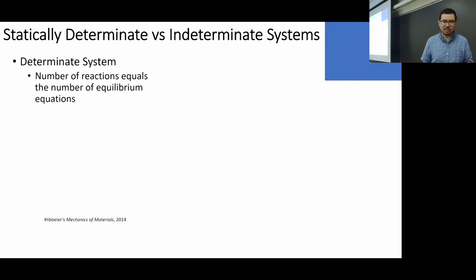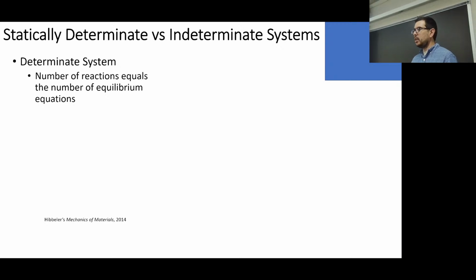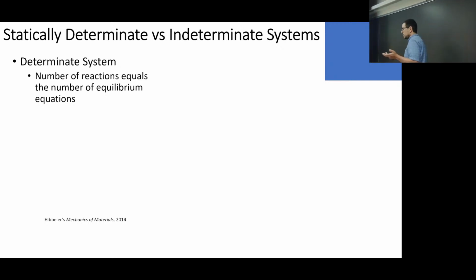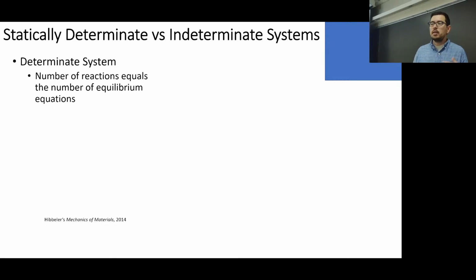That's right. So when you do equilibrium, when you perform the balance of forces and moments, you're going to get a situation where the number of unknowns is greater than the number of equations that you have. And so our typical process is to think about having to use geometry and constitutive relationships to be able to solve the problem.